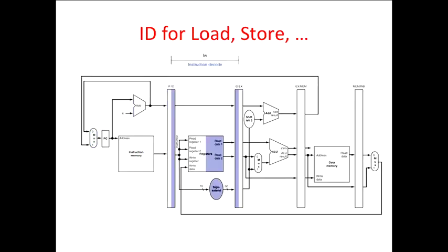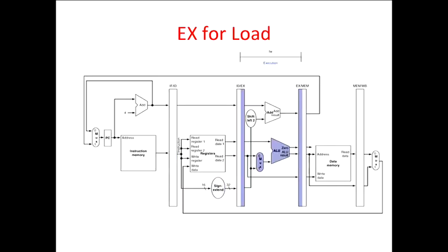So now that first instruction moves to the next clock cycle, and we do the decode for that next instruction. So it's sitting in this register. We do things like sign extend the immediate in here. We also read the 2 register operands, and we capture all those in more registers. So you have these registers just to capture the data we've got. We haven't done any compute on this yet. All we're going to do in this clock cycle is decode and read the register operands and capture them here.